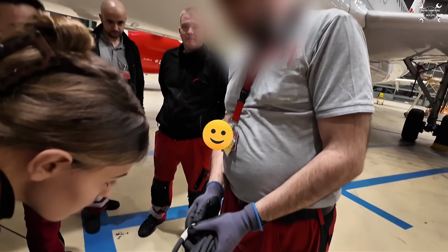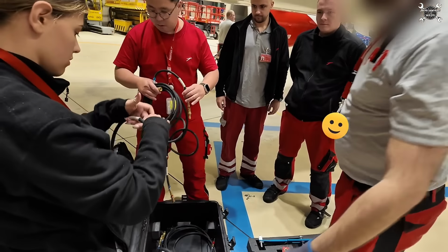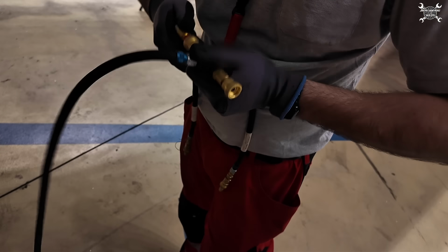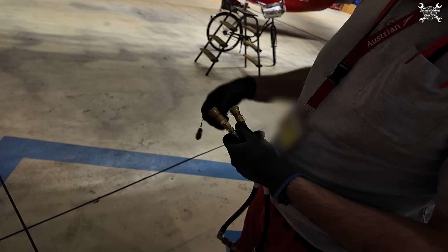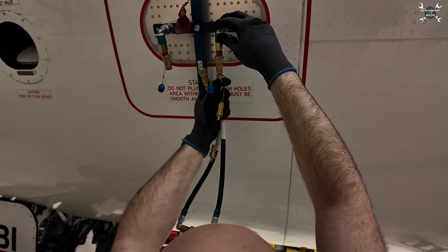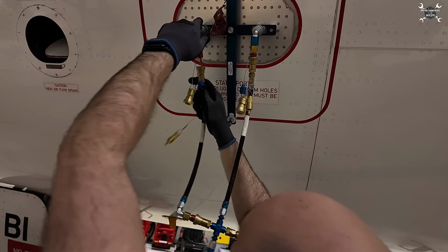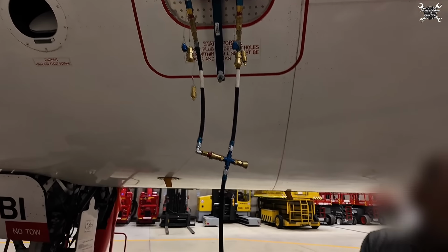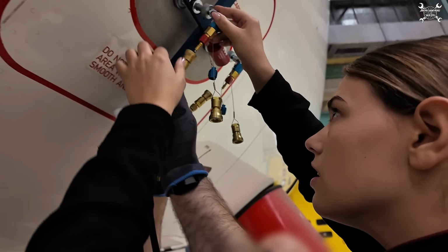So this is standby static left hand. We don't need this. This is static main left hand. So you remove this one. And then when you insert this, you also hold it from this side, and it should click. You carefully insert it because you can damage the pin. So this is from the other side. Just put it in and then it will click.